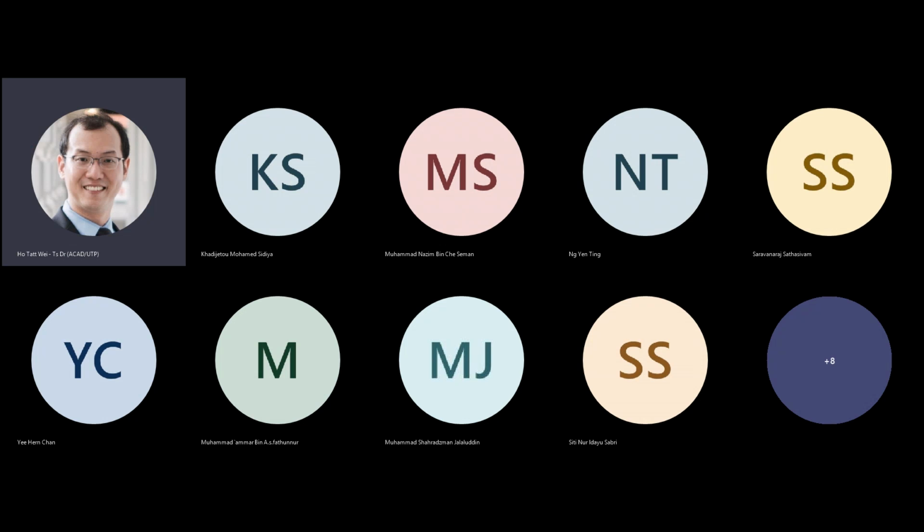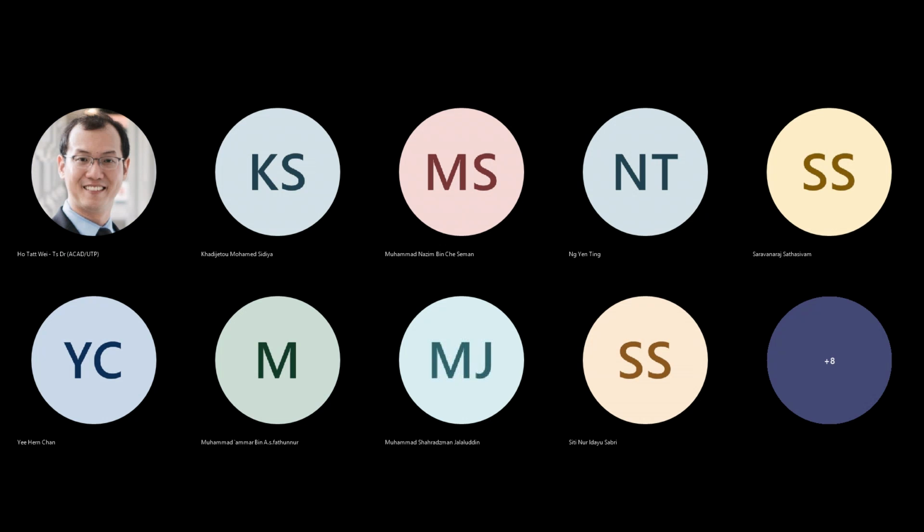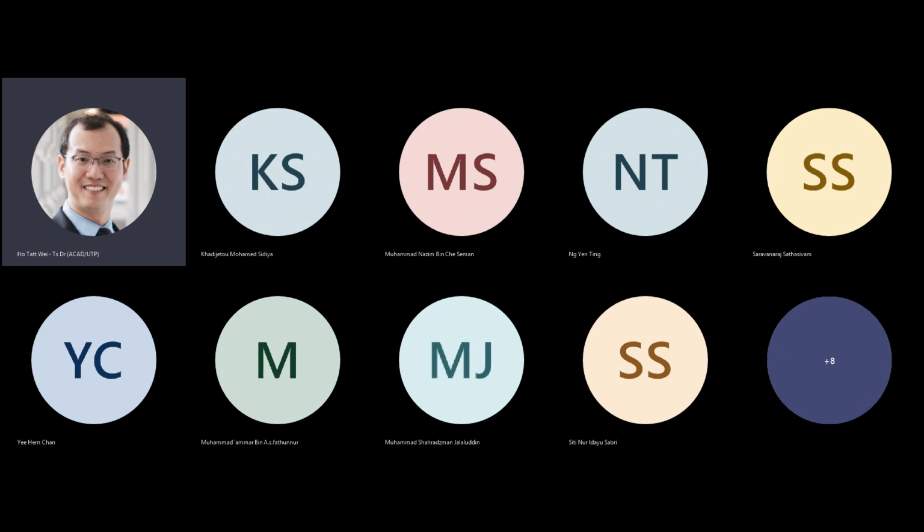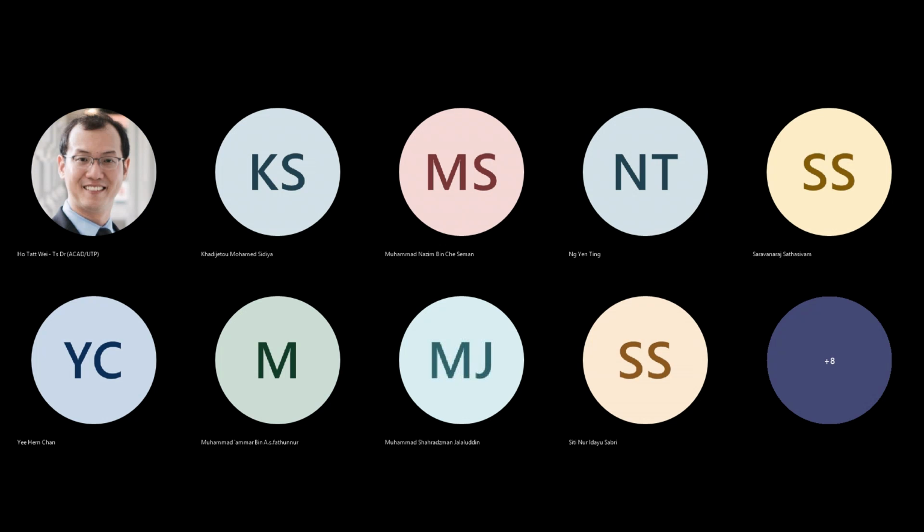So the real relationship is mu Cox W over 2L times VGS minus VTH squared. So this is what we call the long channel model.